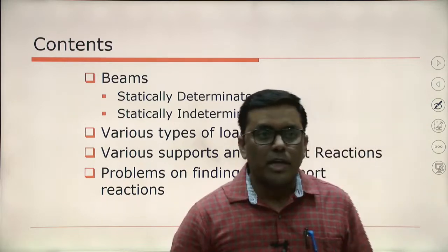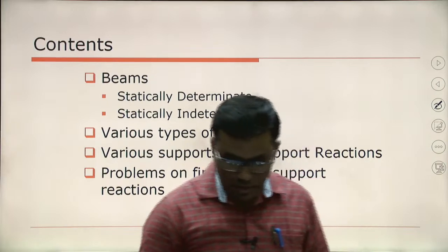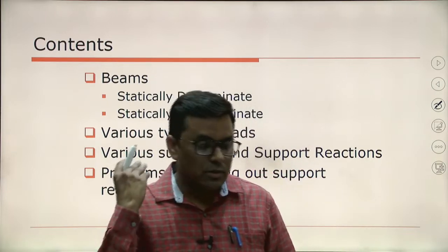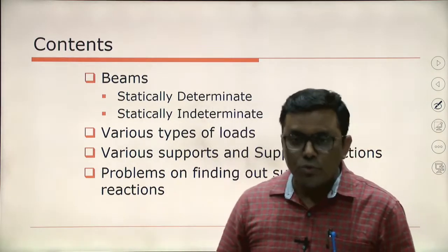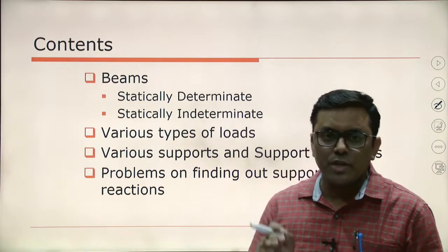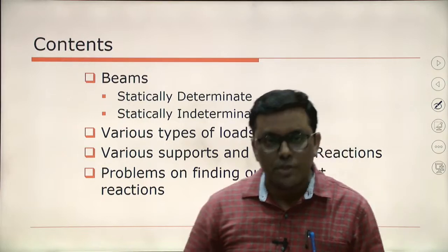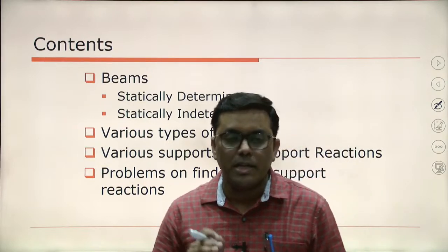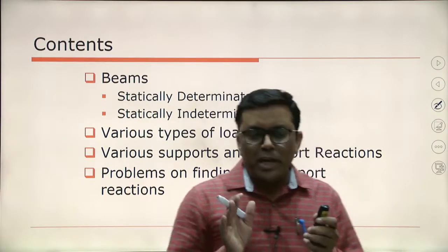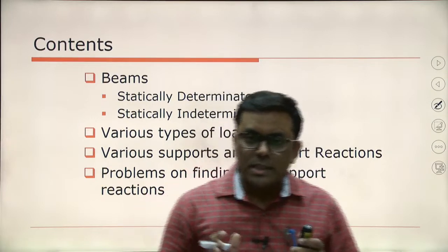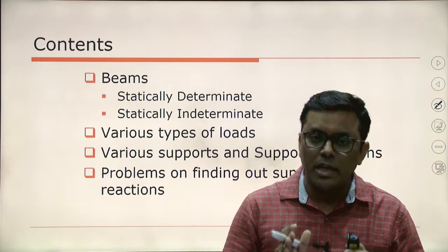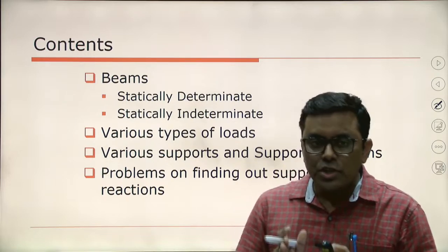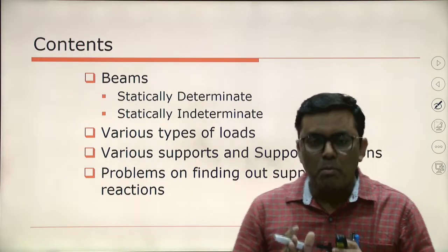This question may come in everyone's mind: why is the topic shear force and bending moment, and I am starting with beams. So the very first question is, what basically is shear force and bending moment? Shear force and bending moment is the resistance offered by beam material against the shearing action and bending action.